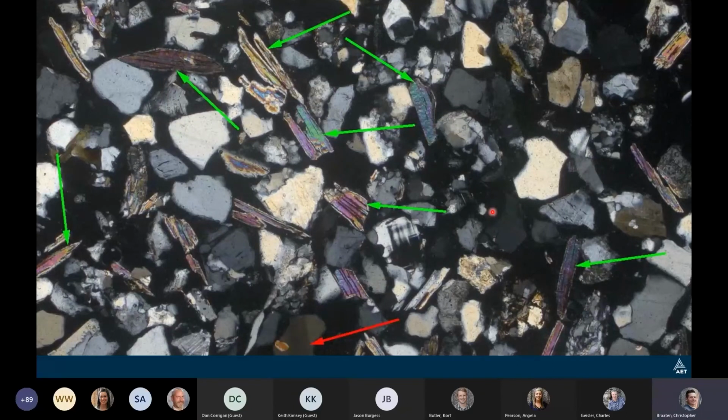That granite aggregate is typically a good aggregate to use, and manufactured sand, if you have a high mica content in your granite quarry and you decide to make a sand, you can start to crush and separate those micaceous minerals out, and it could cause problems in the sand. Probably won't be an issue in the coarse aggregate.